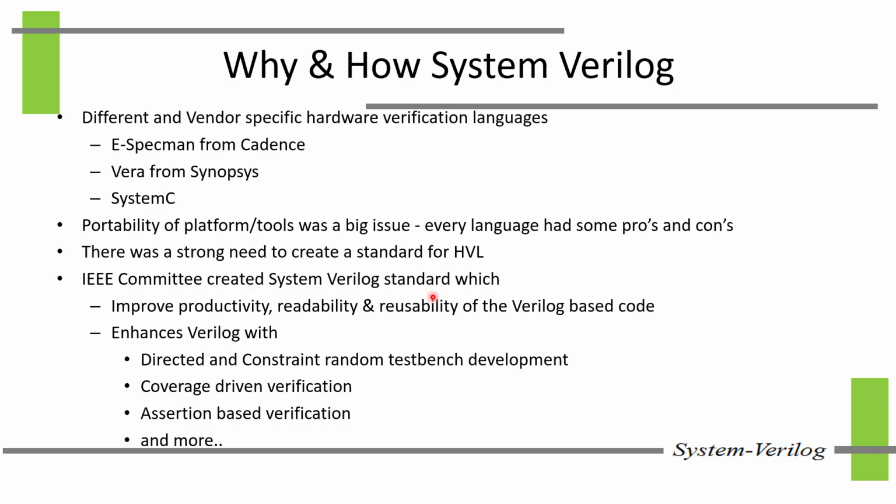Their main goal was to improve productivity, readability, and reusability of the Verilog code. Basically it enhances Verilog with directed and constrained random test bench development, object-oriented programming concepts, then coverage-driven verification, assertion-based verification, and many more features. Now every EDA vendor supports System Verilog. So if you write your test bench in one language, it can run on any simulator.